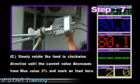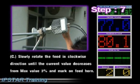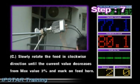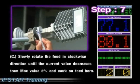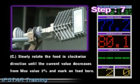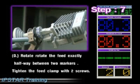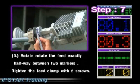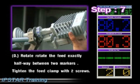7C, rotate back the feed slowly to the peak signal strength point and repeat the same procedure to get the 3% point on the other side. Mark the point with a marker. 7D, point out the midpoint between the two 3% points. Indicate this point with a marker and align this point exactly with the interface of the junction block.